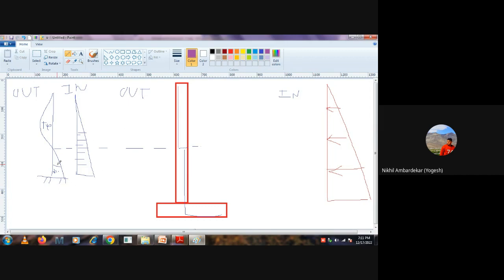Okay. So this is the hogging because of this water pressure. What happened? On the wall, the hogging moment is coming inside, and somewhere at the top outside, the sagging moment is coming. For the hogging moment, which is on the inside, that's why we are providing the reinforcement rebar inside, and to take the sagging we provided bars here.